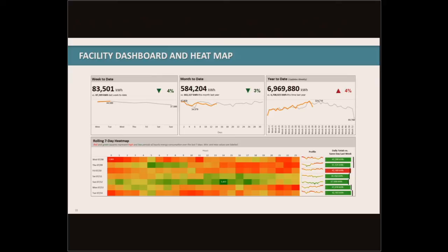And what that can tell us is, just looking here, you can see on the very top left, the most energy during this week was that top left corner. It was about 1,800 kilowatts, and that was on Wednesday at midnight. Well, what happened Wednesday at midnight? Is that a time when we expect the energy to be that high, or was that an area of opportunity? The least amount of energy used is going to be Sunday there on the 14th hour, about 1,400 kilowatts. That certainly seems reasonable. They probably were shut down on a Sunday.